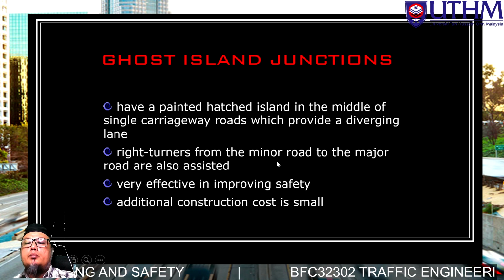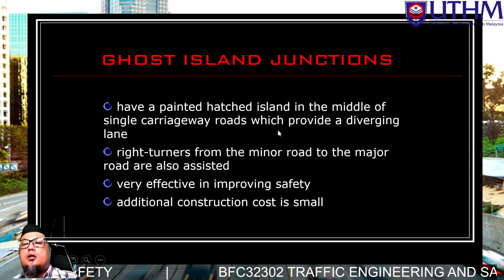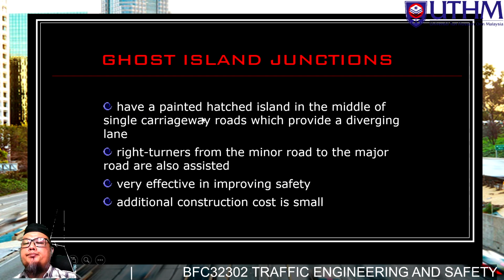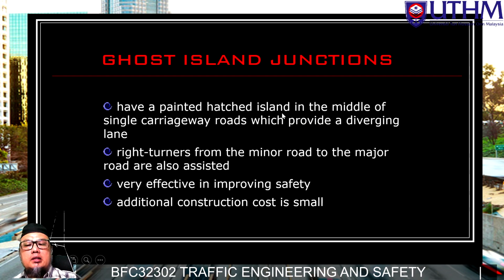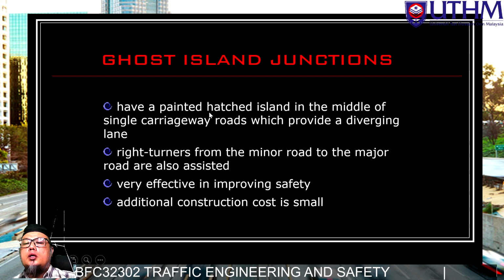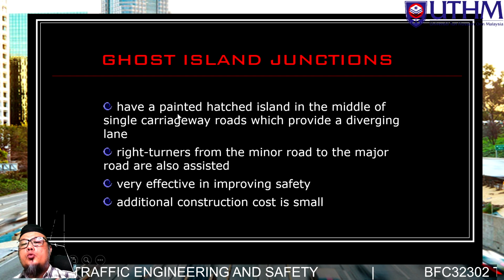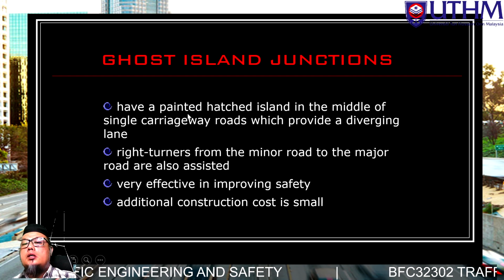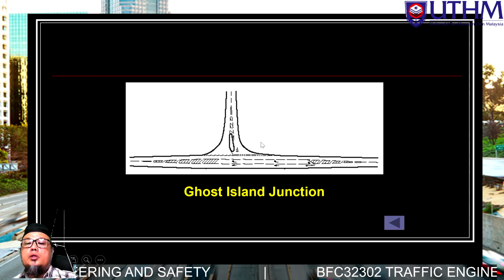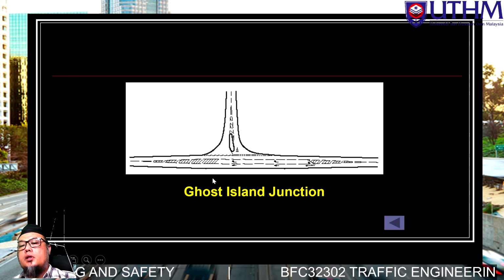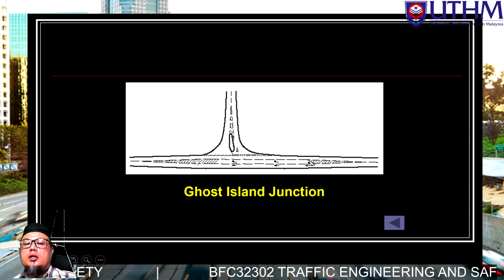Right turners from the minor to the major are also assisted. So it means they will make a guide, or segregate the middle lane a little by providing the Ghost Island. The Ghost Island is like an artificial island, just painted with hatch. So this is the typical layout for a Ghost Island intersection. This part we call the Ghost Island.